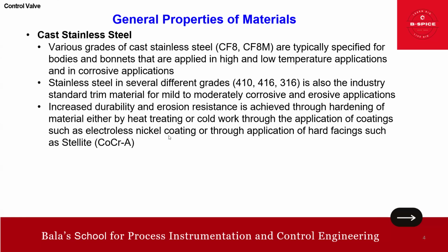So what sort of coating? Like electroless nickel coating or hard facing such as stellite. You would have seen it, right? You would have heard of stellite material, right? So this is basically achieved by heat treating or cold work, or through the application of coatings such as electroless nickel coating or through hard facing such as stellite. I hope this is also clear.